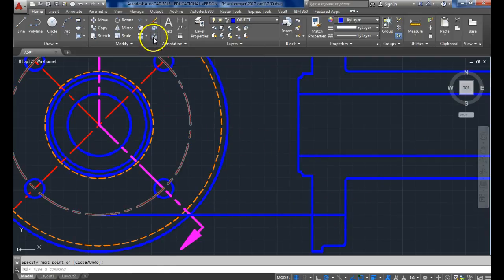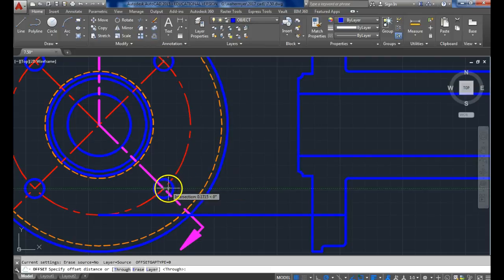and then if I do offset the radius instead of the distance, so these are 0.75 diameter. So it would be, instead of 3/4, it would be 3/8. Offset this up, offset this down. I can delete these two.